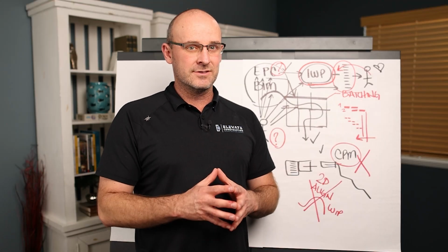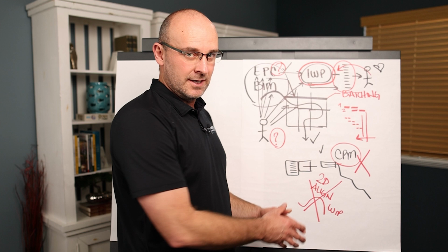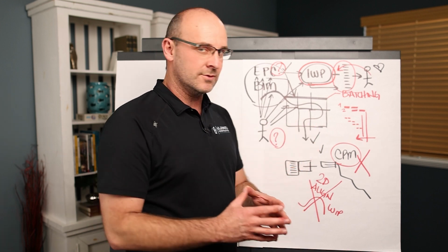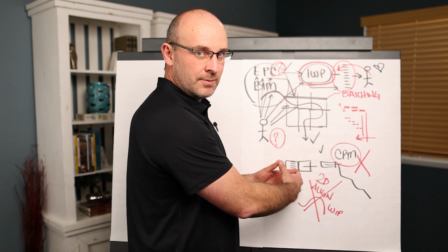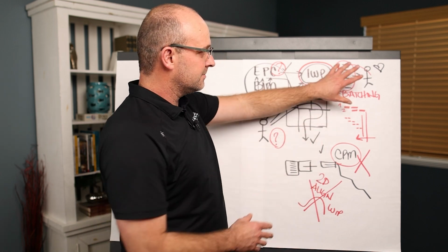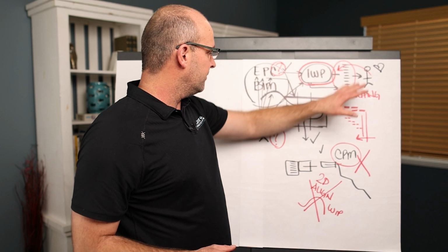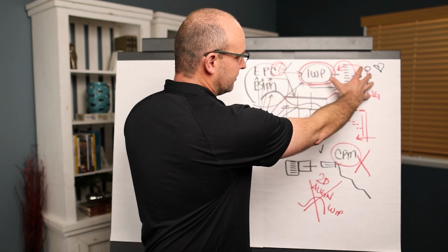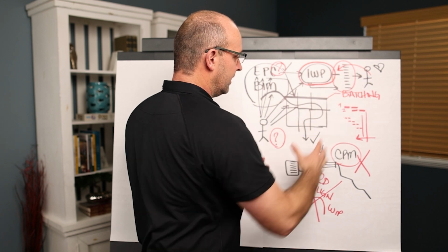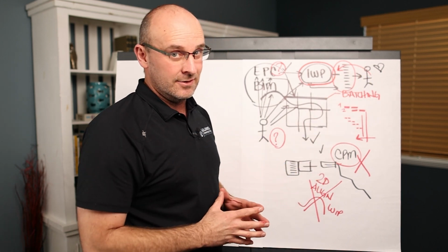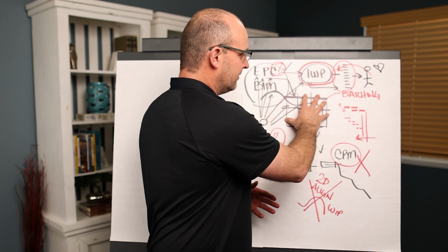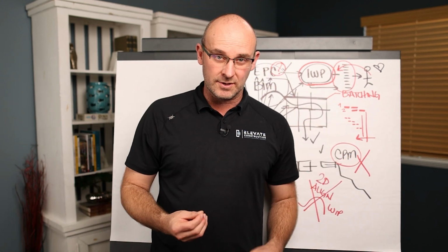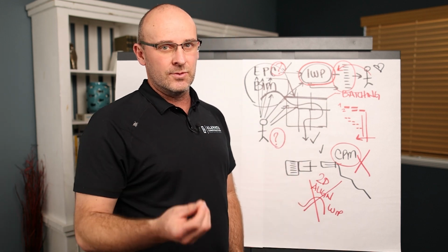So it is a sin to lock ourselves into a baseline with CPM. It is a sin to increase work in progress above the capacity of resources. It is a sin to rush, push, and panic, and it is a sin, according to the last planner system, to command and control foreman, and it is a sin in lean thinking to disconnect the actual planning and decision making from the people boots on the ground. And it is a sin, according to production theory, to identify large work areas without using the TACT calculator to find the right zoning strategy. So these are some things that you really need to look out for.